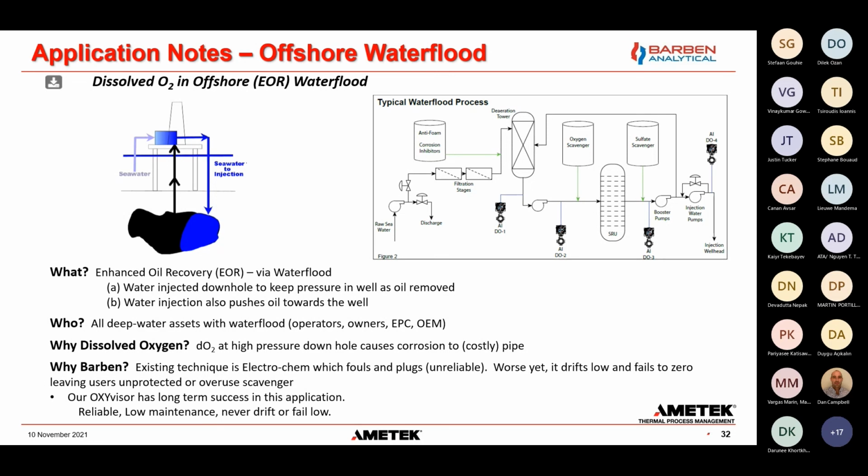So to be able to overcome that, you grab some seawater and run it through some cleaning processes and downhole. This is a very high pressure application. As we said before, oxygen can be extremely corrosive to metal in high pressures, and so this is that case. We need to remove the oxygen before we put it downhole.